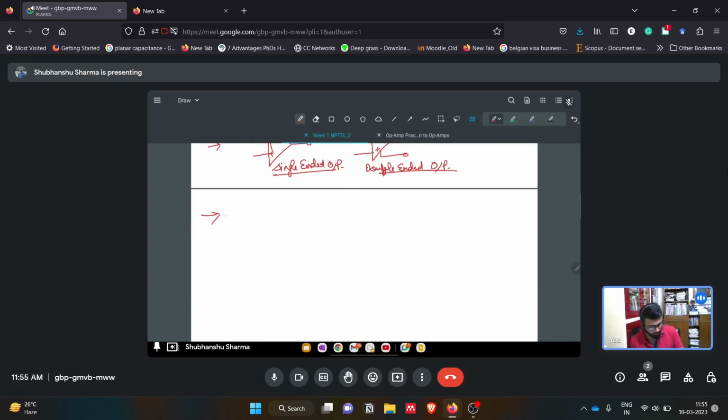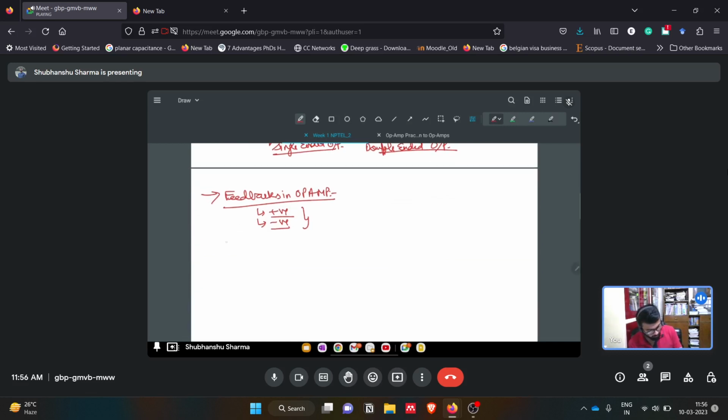So now if we talk about the feedback in op amps, we can have either positive feedback or negative feedback. But first of all, why do we need feedback? We know that the gain of the op amp is very high. So if we say the open loop gain of the op amp is approximately, let's say, 200,000.